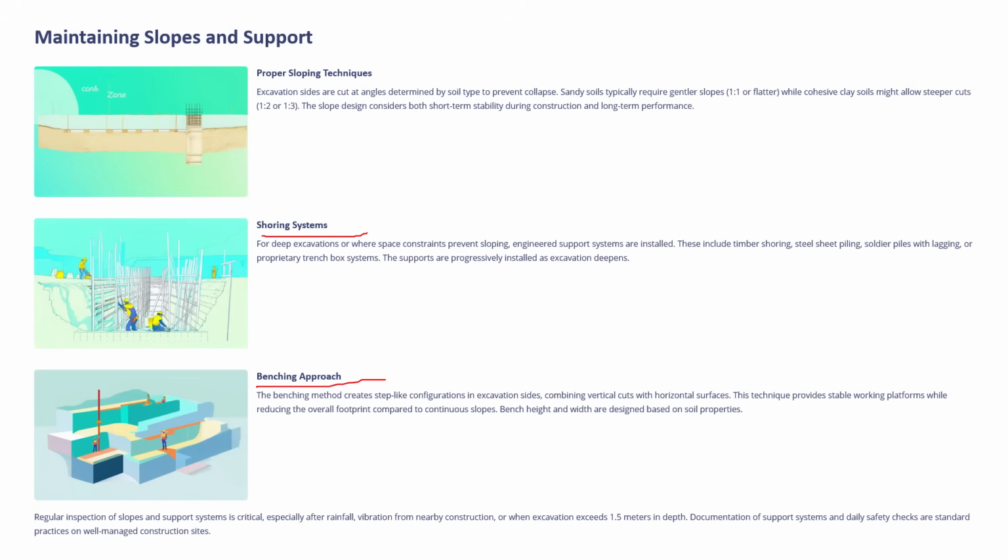Regular inspection of slope and support systems is critical, especially after rainfall, vibrations from nearby construction, or when excavation exceeds 1.5 meters in depth. Documentation of a site's support system is very essential, and daily safety checks are standard practice on well managed construction sites.